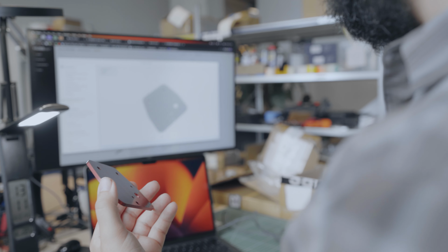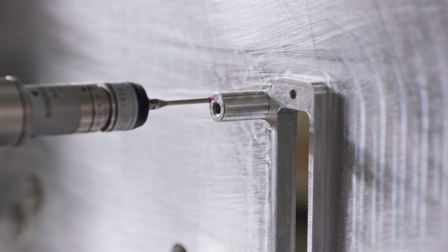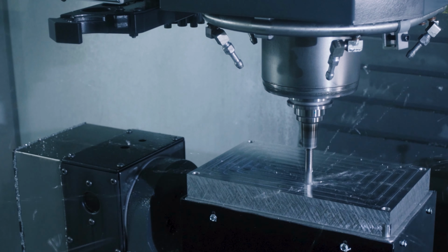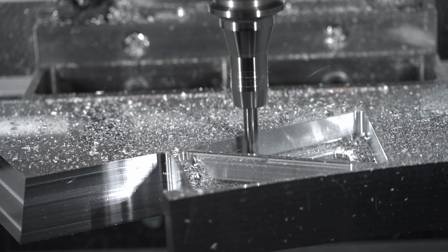Where precision is less critical, use industry-standard tolerances like plus or minus 0.1 mm for general dimensions. This reduces the need for expensive precision machining and simplifies quality control. Removing tighter tolerances also improves the repeatability of the part and allows us to cut costs.